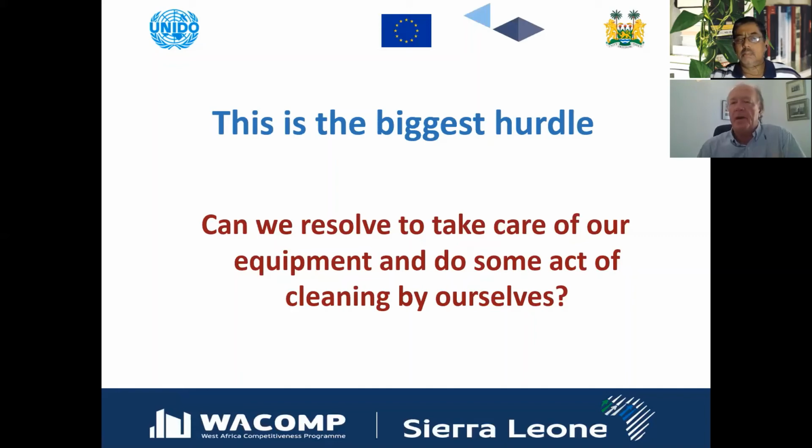If the equipment in the manufacturing plant is dirty and messy and there's oil all over the place and dust all over the place, it's very difficult for us to see if there is an oil leak. But if we keep our equipment clean and tidy and the floor under the equipment free from clutter and free from messy things, we can immediately see if there is an oil leak. And we can start to do something about that, either by ourselves or by calling somebody from maintenance before it's too late, before the equipment breaks down, before the equipment overheats, and so on.